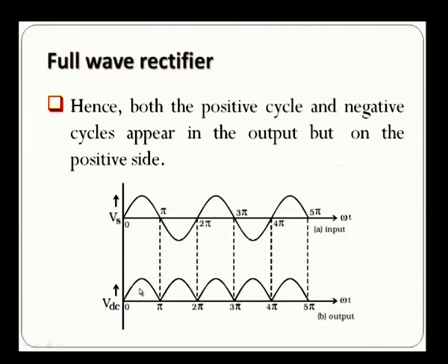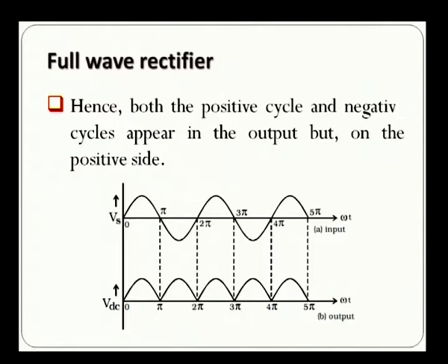Because the variation is happening only on the positive side, it is considered as a direct current or direct voltage. When we consider direct current or direct voltage, what comes to our mind is that the voltage or current should remain constant with respect to time. Is it happening like that in this case? It is definitely not. There are ripples formed in the output waveform. Ripples are the variations, the change in the voltage, that is happening in the output potential that we are getting.